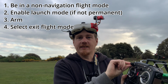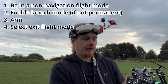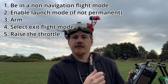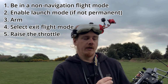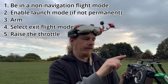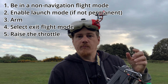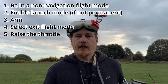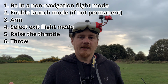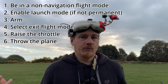Now we can select our end flight mode. So I'm going to put mine in loiter, and then the next step would be to raise the throttle to the exiting flight mode throttle level. So when it finishes the auto launch, it will be at the throttle you set now. I'm just going to disarm quick because I don't want it starting on the floor. Once I've raised the throttle, the next thing that will happen is the 5-second delay for the idle throttle. Once that kicks in, we can throw the plane and get it up in the air. So that's what I'm going to do now.